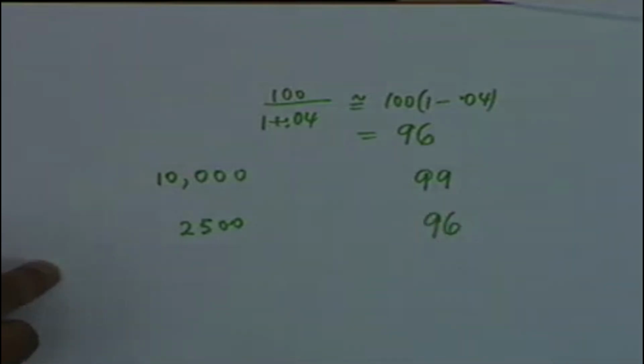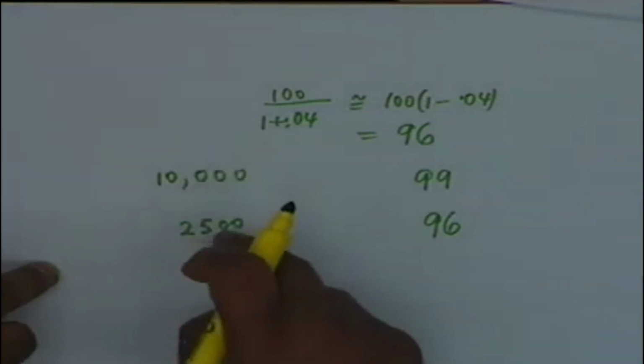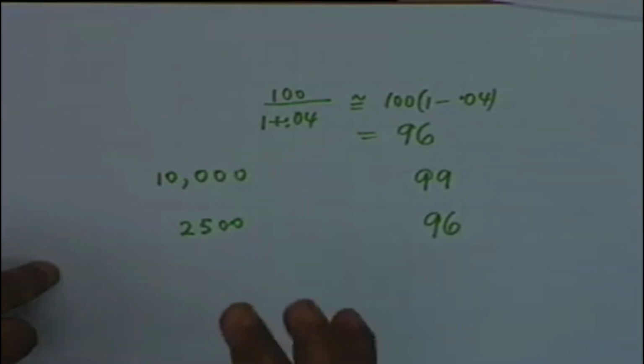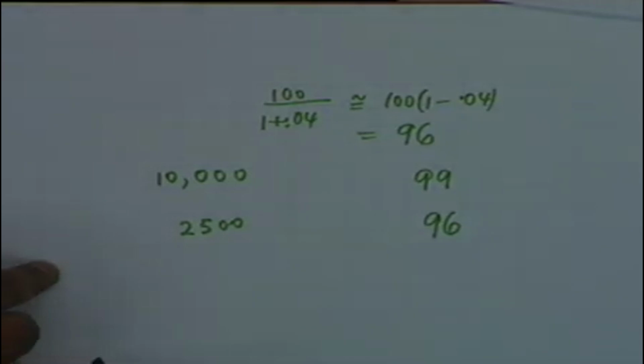Is that clear? A 75% change here is reflected only as a 3% change, and therefore the gain becomes insensitive to the gain of the internal amplifier. Whatever the cause, internal amplifier gain may change due to change of temperature, due to change of device, or whatever it is.